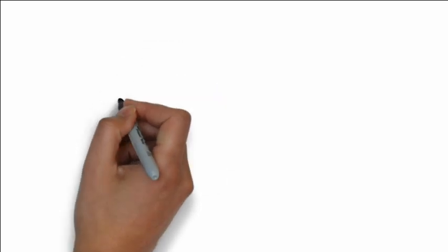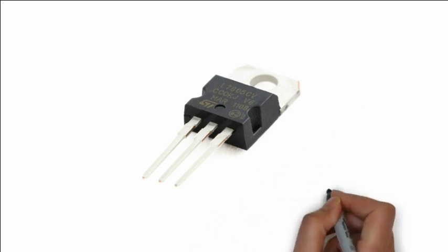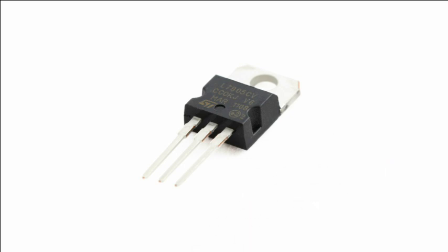So let's start. Often, while dealing with electronic circuits, we find it a necessity to regulate an input voltage source to fix a stable output voltage. Also, voltage fluctuations in the circuit need to be stabilized to make the circuit function in an authentic order. To meet this purpose, in a handy fashion, we have the 78XX IC series. The XX here defines the output voltage catered by it to the circuit. In our concerned video of IC7805, the XX is obviously 05. So the output stable voltage is plus 5 volt to the circuit.